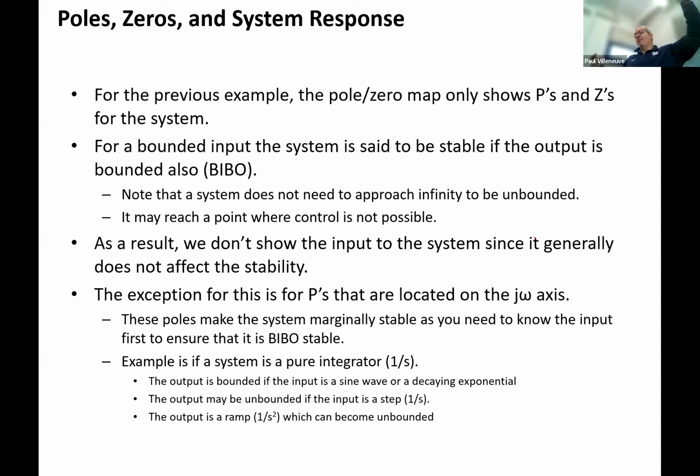So that's why some boilers today, you can run 700-800 degrees. If you're in a steam cycle at a power plant, they're pushing 1,000, sometimes 1,100 degrees of temperature. You got to run it up to 2,000 psi, because you have to be able to bring that steam back to water at some point. So if it goes into the steam turbine, before it gets there, it's got to be actual water, and you don't want it to be at 200 degrees. So you actually have to pressurize it pretty high, because you don't want a huge delta between the two. By the way, anybody know why temperature limits of 1,100 degrees or so kind of limits most thermal cycles? It's a more obvious answer than you think.